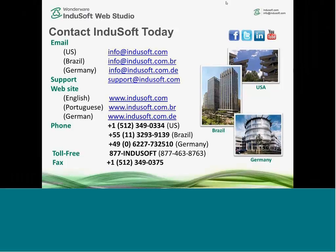Great question. The way that InduSoft works is we don't compile the project. We work off of configuration files. And part of what that means is it's quicker to deploy. It's very efficient. And when using thin clients, it's not like you're streaming video like a remote desktop solution might need. It actually sends the screens, and then it gets the data really only on exception basis. So it's extremely efficient in how it gets that. You really don't need a very high-end PC to be able to serve this up.